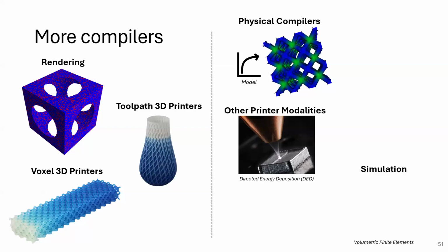So when we talk about these material gradients, we mostly talk about them graded in the X and Y axis, because it's the easier toy example to talk about. But as we get into interlayer bonding, that's a separate branch of research that people look at: how can we improve interlayer bonding? If we know that we're printing with materials at two very different temperatures, for example, ABS is going to print really hot, a high temperature material, versus PLA, which is a lower temperature material.